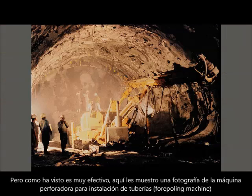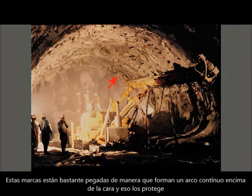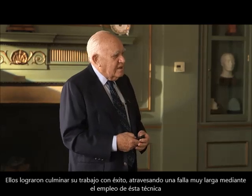And there's a photograph of the forepoling machine drilling the forepoles, and along the arch there's a step, and you can see yellow marks where the forepoles are going to be installed, and they're close together and form more or less a continuous arch above the face to protect you. And they successfully work their way through a very large fault using this technique.